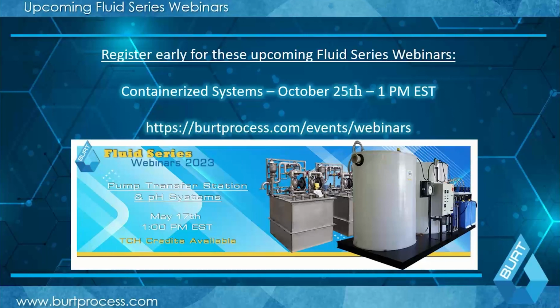One of the questions we have here is, I'm not sure I understand why you're saying you can't use diversity for a lift station. The reason we don't use diversity for lift stations as much is the difference between a lift station and a gravity flow system. When you have a lift station, you have a small tank volume, and you have to assume that if anything doesn't go through, your only means of leaving is through the pumps.